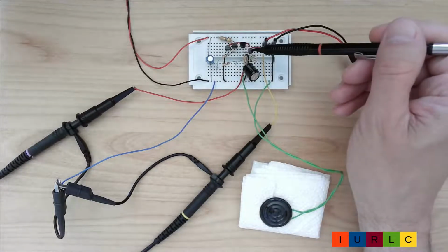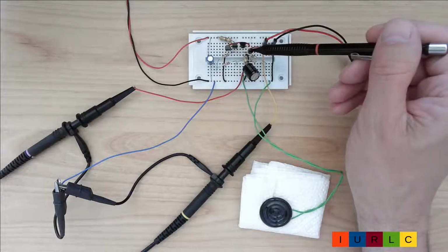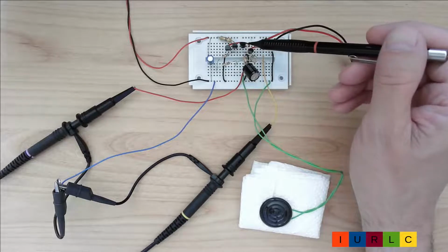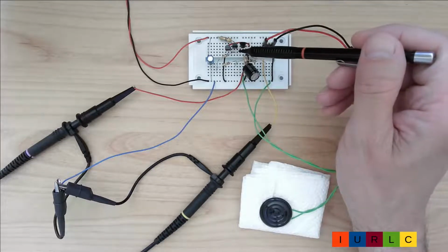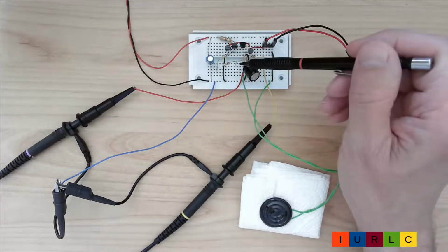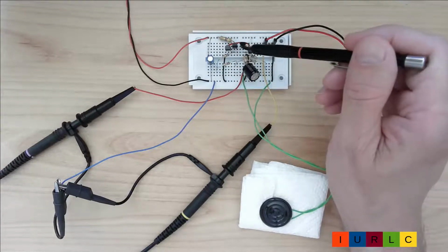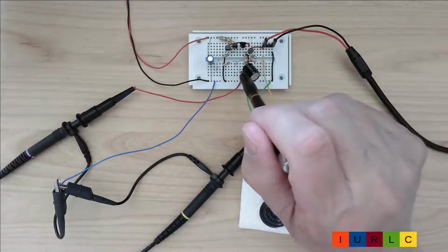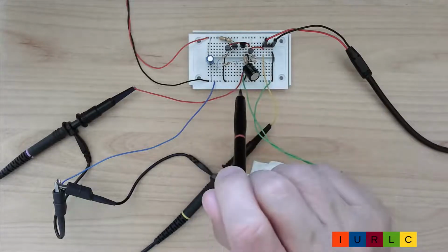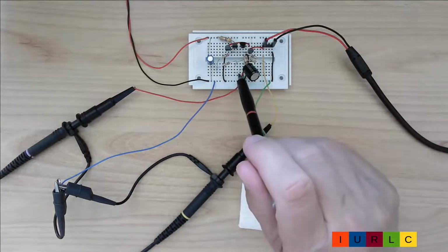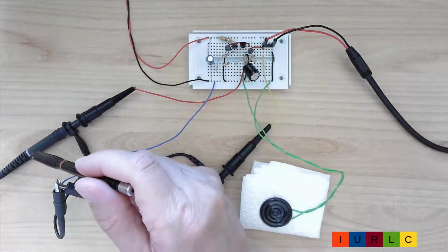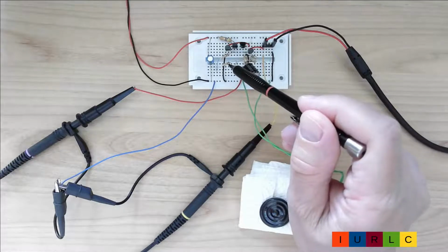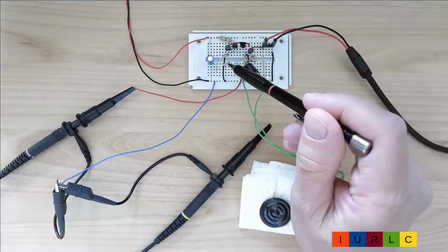We have here the input transistors, the PNP and NPN, and the output transistors, the NPN and PNP. The emitter of the output transistors goes via two 1 ohm resistors to a middle point here and here, and the middle point goes to the capacitor, and from the capacitor we have one line to the loudspeaker and one line to the purple oscilloscope probe. I have used here two single 1 ohm resistors because I have no 2 ohm resistor available.